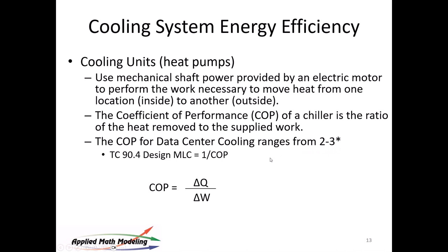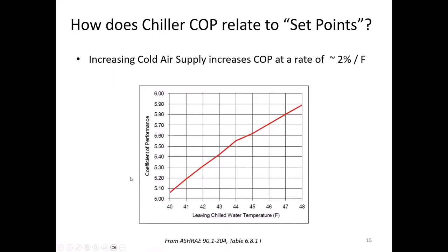They always measure it in the United States. They always do kilowatts per ton, right, Magnus? Yeah, exactly. Talk about mixing your units. But if you neutralize the units, it ends up being somewhere around 3 or 4 on a good day for a typical chiller. So thermal load in the room compared to the energy to remove it. I tend to think of COP as for the data center itself, which is more like an MLC kind of calculation. So, chillers in the range that we tend to work tend to be fairly flat.